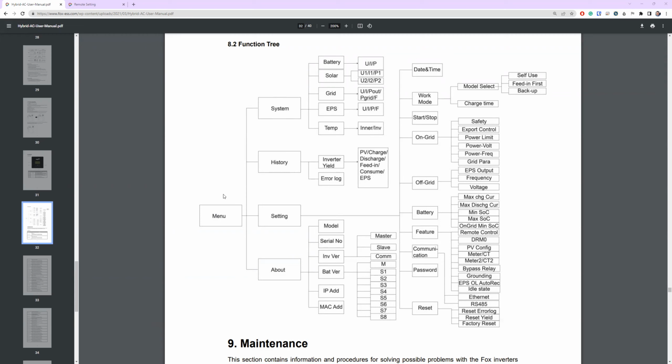So when you've got the inverter screen, you'll press the furthest right button, looks like a backwards button. That will cause the screen to light up. And then if you press any of the other buttons, or the check mark, which I think is the third button, you will see these options: system. In fact, they're actually in a different order, I believe. I think it's system, settings, history, then about. But you'll find them. You can cycle up and down.